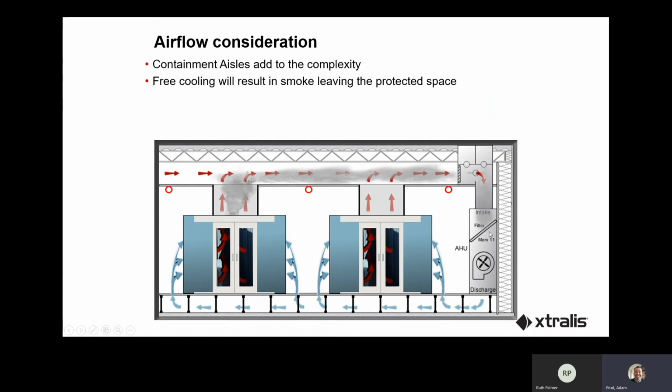So in all cases, when there's an air handling system, the air handling unit will draw airflow back to it, but the intake grill may be remotely positioned based upon what airflow is happening prior to that air handling unit. So in this case, this example is showing a closed system. So we're recirculating the air through the air handling unit, past the filtration, past the cooling, and back into the floor void.